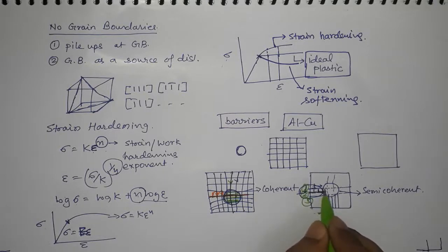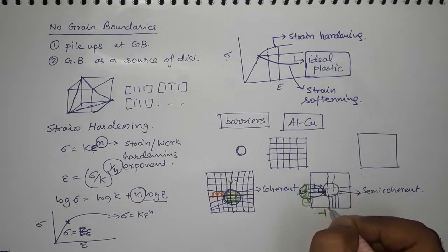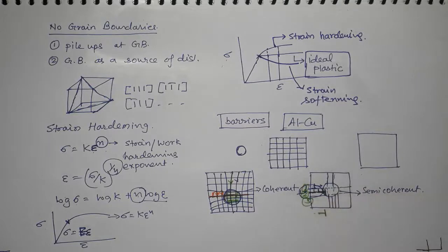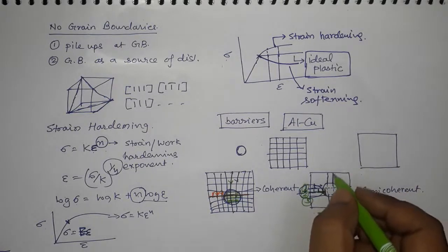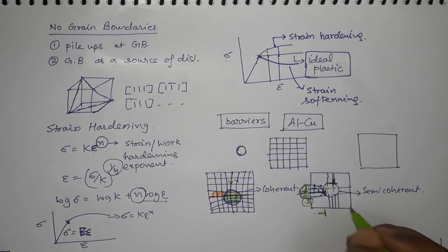So you have to put a dislocation there, and then it's okay, right? Again, you see that this has a matching inside, and then the second line has no matching inside. So this second layer, this line, is actually a layer of atoms, and that layer of atoms is missing inside. So what is that? That is again another edge dislocation, right? So in a semi-coherent interface you will have a lot of dislocations there.